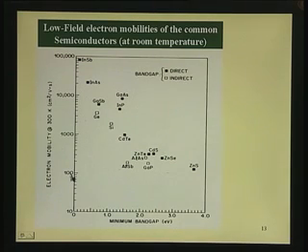I hope it is a scanned one, because I thought it is better to put that, because it is something which is standard, projected everywhere. 100, 1000, 10,000, 100,000 centimeter square per volt second. You will not believe unless you see this point there, which is really put, that you can have electron mobility at room temperature as much as about 80,000 centimeter square per volt second.